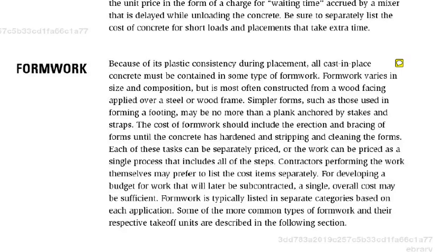If we have some time, maybe we'll look at them, but right now you're going to make a best estimate as far as form work and go from there. But you do need to calculate the cost when you're doing form work of the material you're using, the time to build forms, and the time to take the forms down.